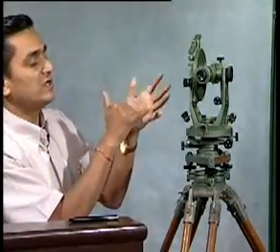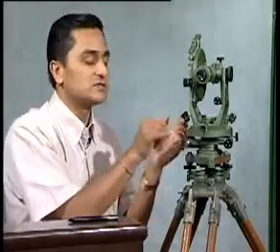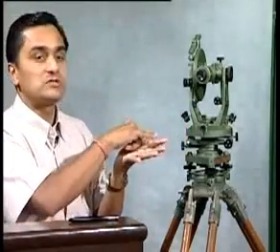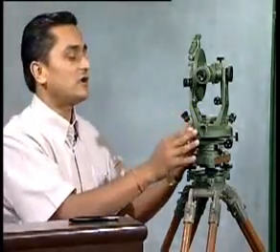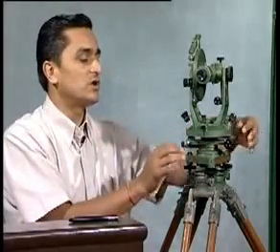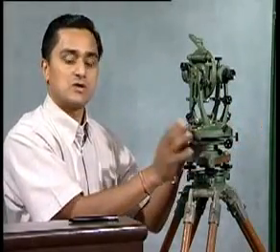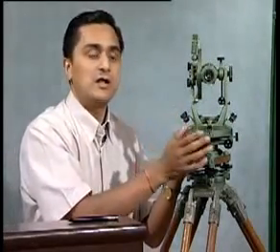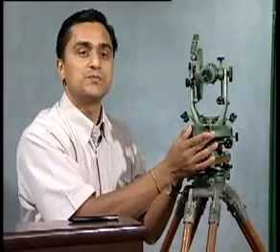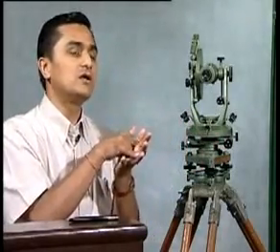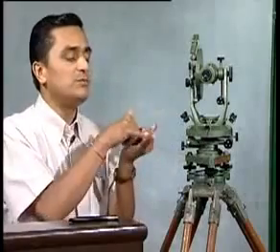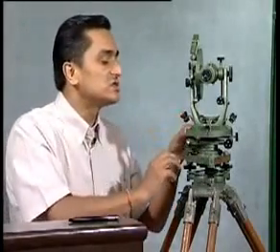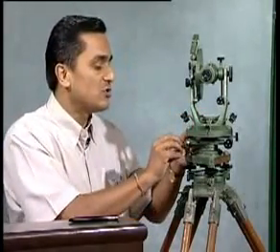So the readings, what are the readings? These verniers are moving on the graduated circle, and we take the reading. We read the angles against these verniers. Because they are moving, the angle values are changing there. So right now the lower is clamped, the upper is free to rotate, so the readings are changing. Okay, what I do, I change the readings, looking through the window here, and I bring it nearly to 0, 0, 0. What is the meaning? The 0 of vernier and the 0 of main plate meet each other. So now at this stage they nearly meet each other, and I clamp the lower one.